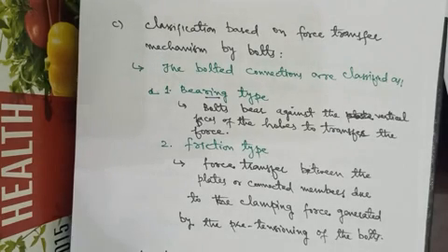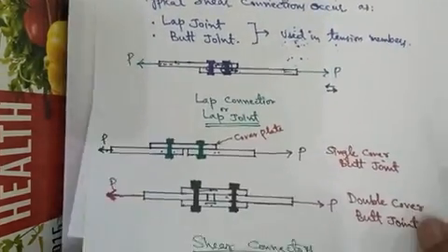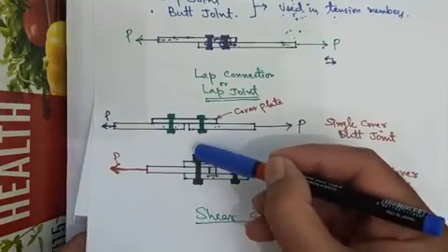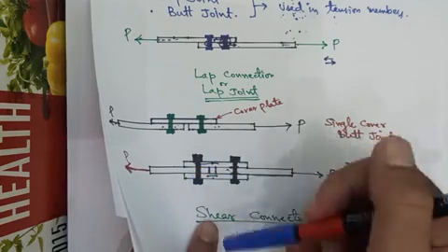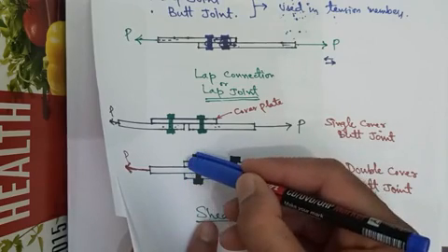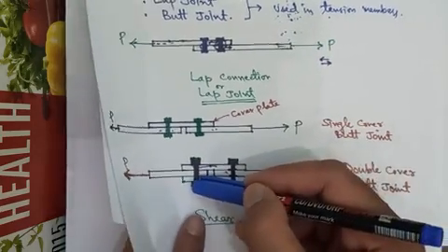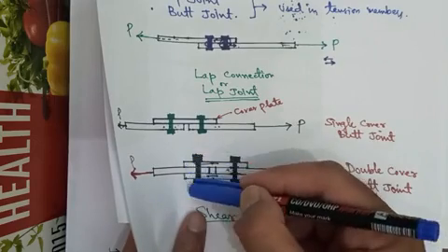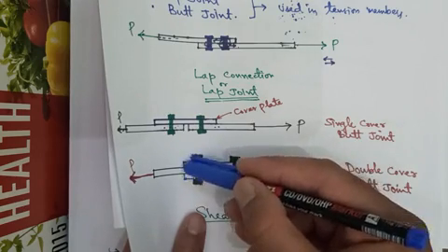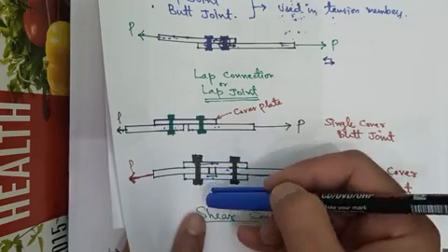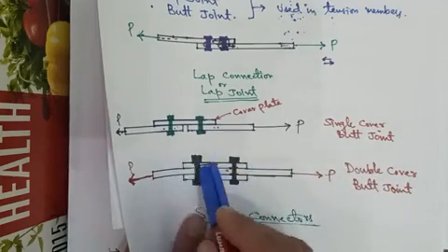That is, when the nut on the other side of the bolt is tightened, pre-tension develops in the bolt, and as a result a force in the vertical direction gets transferred to the two connecting members, and a frictional force is developed between the plates.